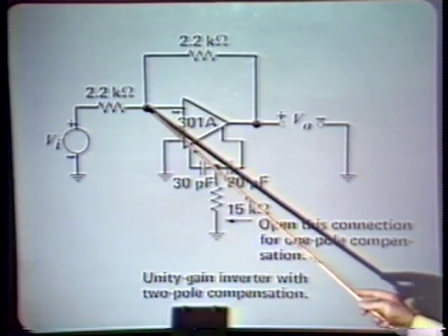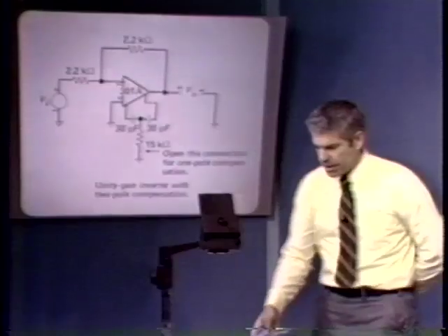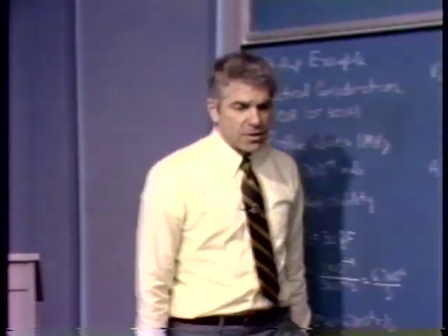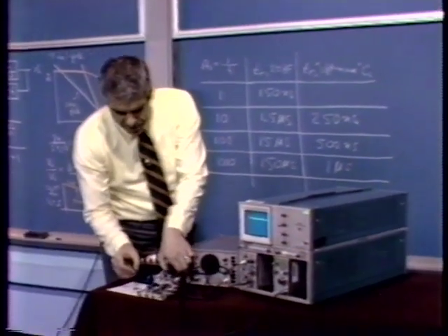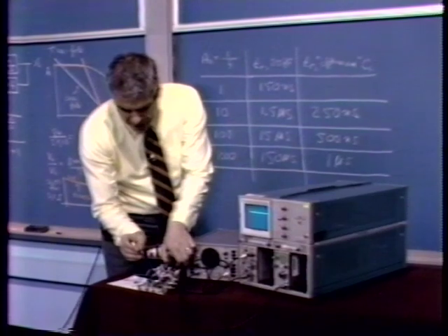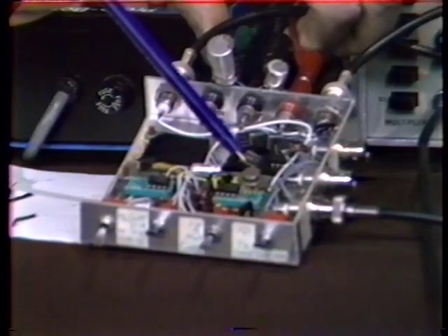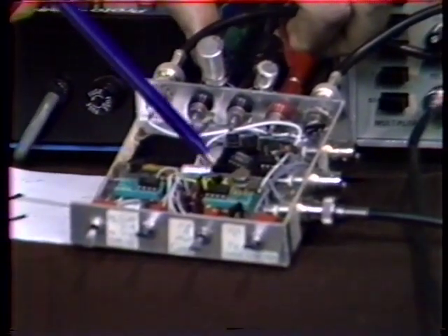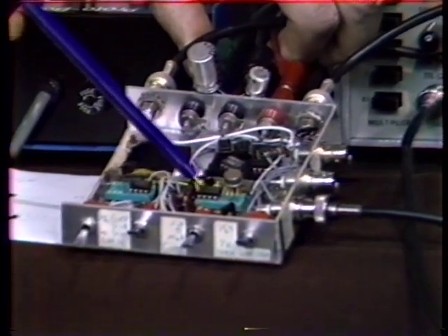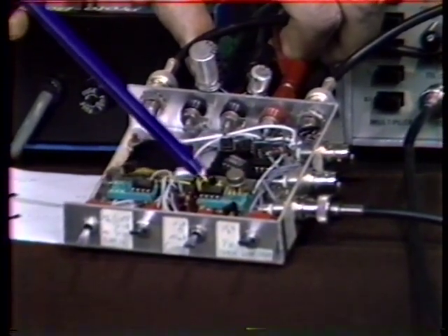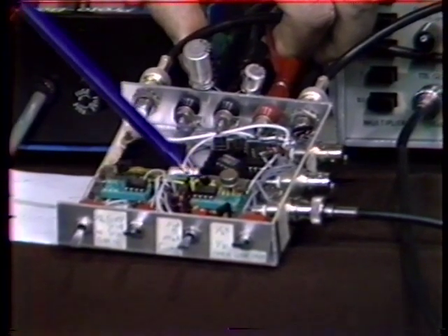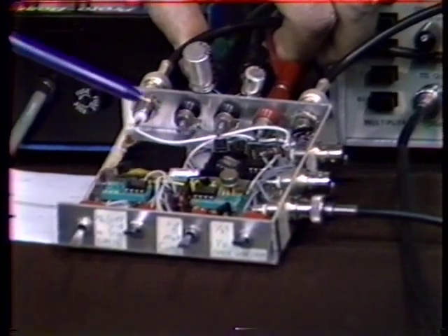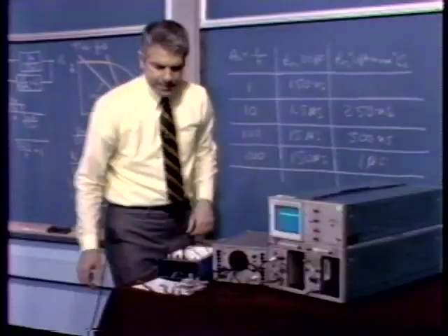And so this configuration allows us to readily look at the error of the system, and that's the reason that we use it in preference to the non-inverting configuration. So, as I say, we have that amplifier here. We have a buffer amplifier that allows us to look at the error signal and present that signal on an oscilloscope when we wish to. And we're able to very quickly change from 1 over s to 1 over s squared compensation, maintaining crossover frequency, by simply lifting the resistor in the middle leg of the T.